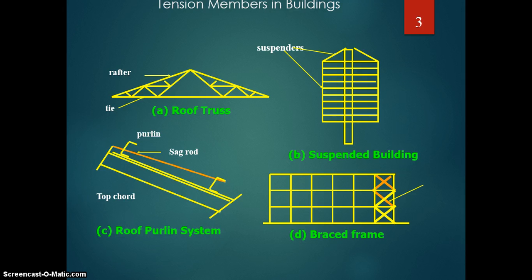The tension members and the connection should be so arranged that eccentricity in the connection and bending stresses on the member are not developed. The strength and efficiency of tension members may be seriously affected by the end connections, maybe bolt holes or riveted connections, shear lag, or reversal of loads causing buckling, and bending moments due to eccentricity in the end connections or lateral loads on the members.